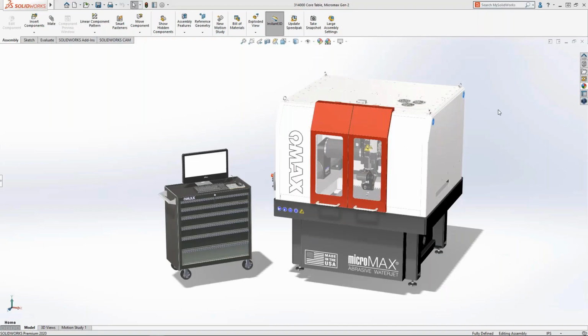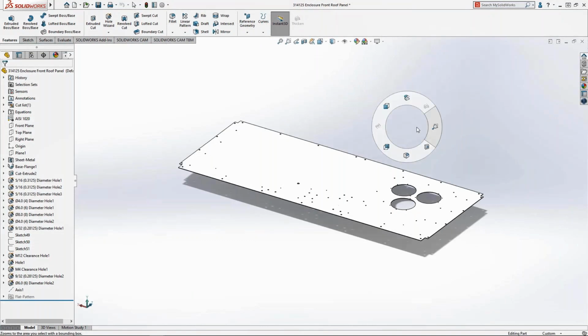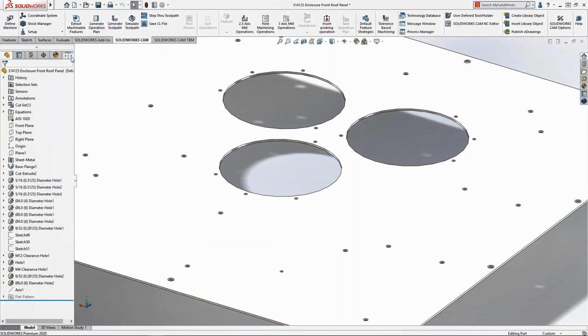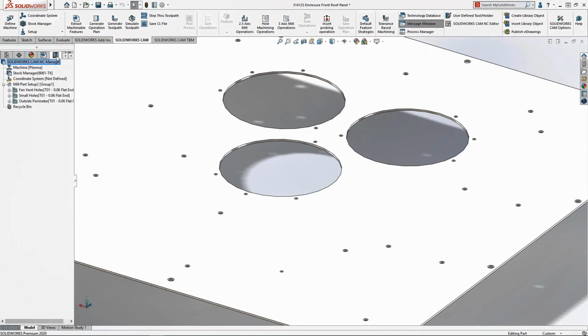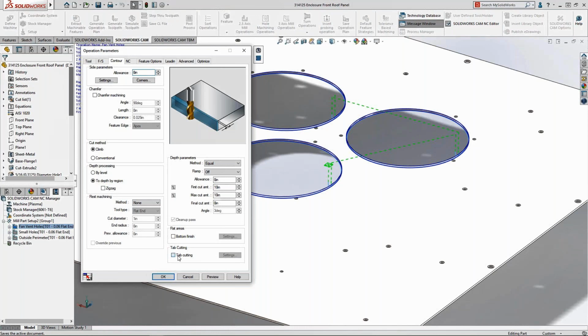The first of which is the ability to do tab cutting. So if we take a look at the traditional manufacturing setup for this sheet metal part, it's going to likely be a water jet or a laser or a plasma cutter. The problem, though, is these large holes when you're cutting something like this. If you think about what happens to the piece of metal from the middle once it's cut, the circular disc can certainly move and interfere with the remaining cutting operations.